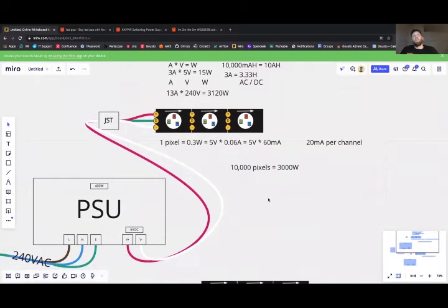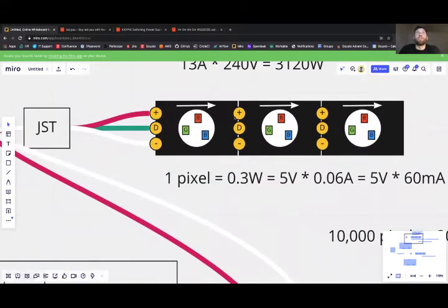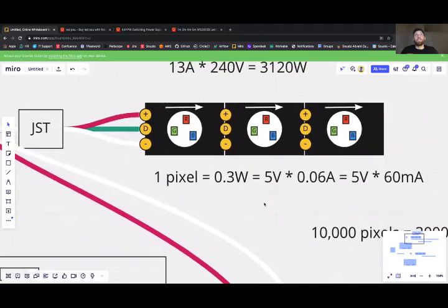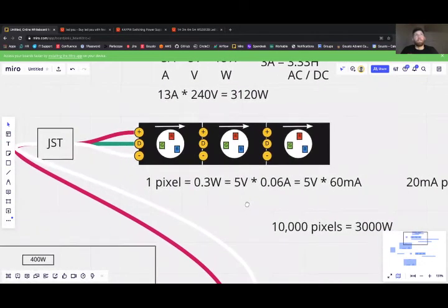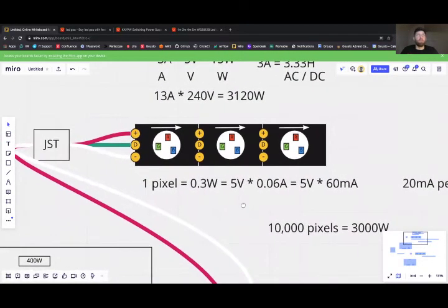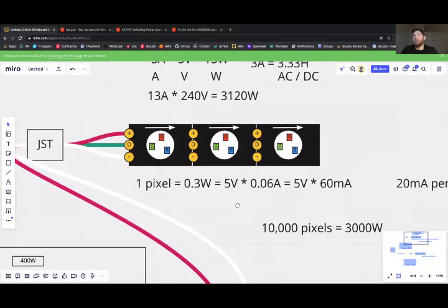Now, where does power injection come in? So it just so happens that these wires inside the printed circuit board also count as cables, and for that reason, they also have the capability to incur voltage drop themselves.